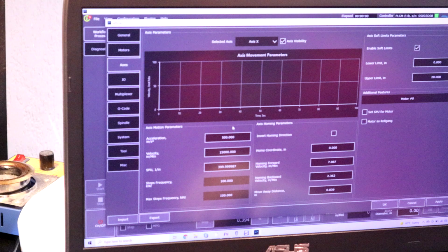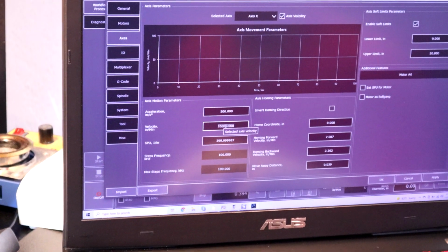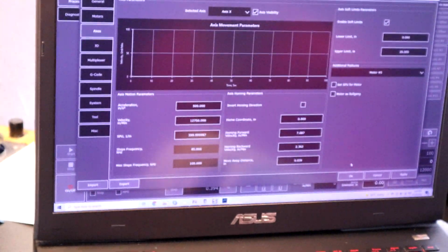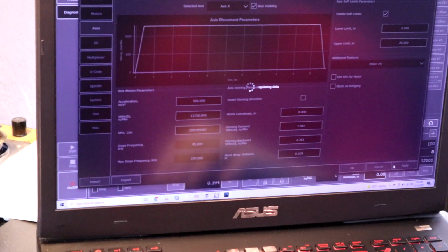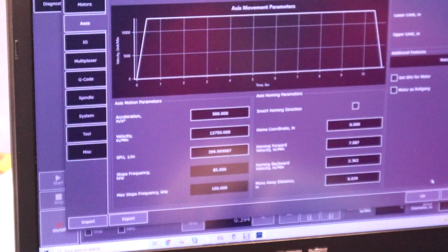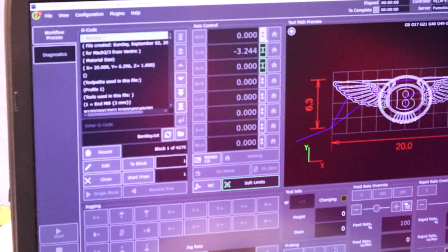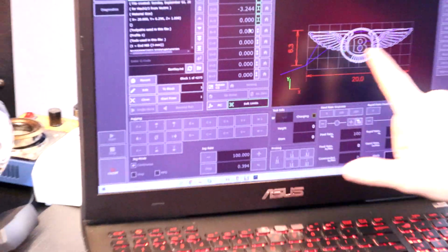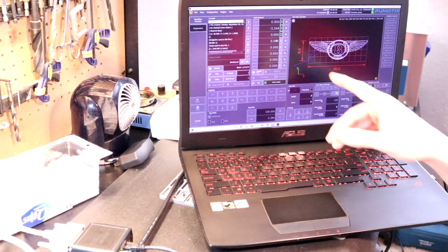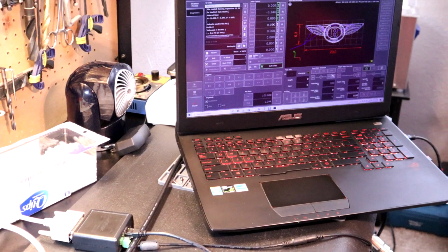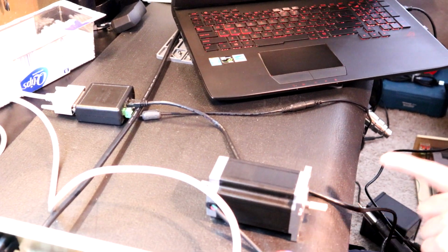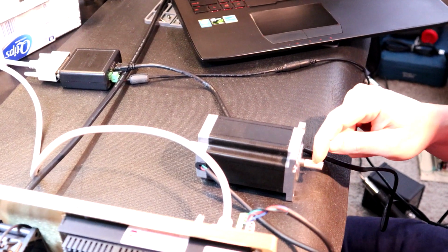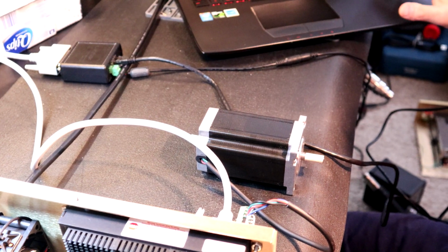here's what's interesting. If we come over here, we'll leave this, we'll go back to his 12,750. We'll be at his same settings, okay? And here's why I turned off soft limits. I'm just applying everything. If I turn my soft limit on, I want to show you this table is fictitiously set at 20 inches in terms of the dimensional aspect for my soft limit to become active. Watch how small a distance this stepper at that setting of 400 steps per inch has to rotate to actually hit the soft limit. Watch this.